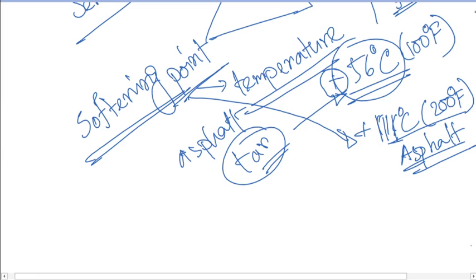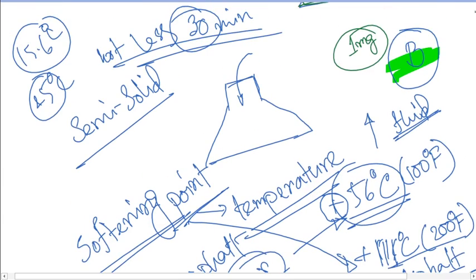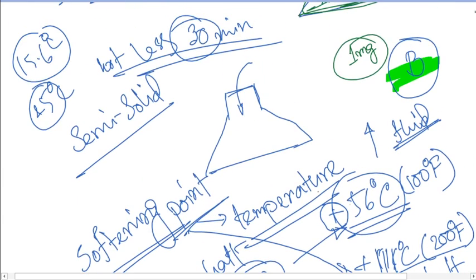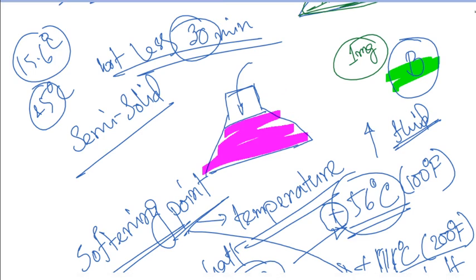If it is already heated and fluid as we expect, then quickly pour that material into this pycnometer, or the cylinder, whichever you are using. We will be targeting to fill the pycnometer with tar up to about 3/4 of its total volume.